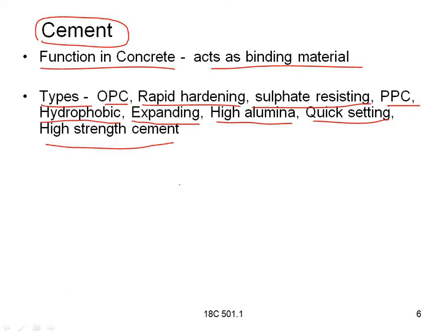Here the 33 grade cements are used for small petty works, like plastering or in footing cases. Whereas the 43 and 53 grade cements are used for high strength concrete works, starting from the foundation to the top of the building in slabs, columns and beams, or in the staircases and lifts.